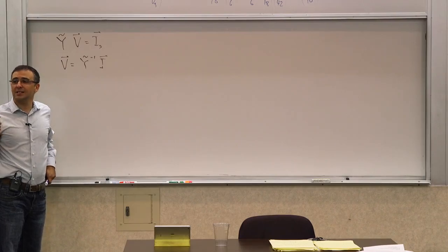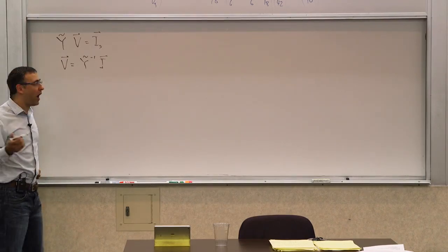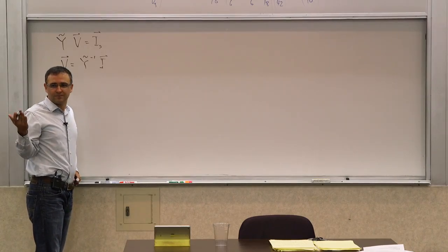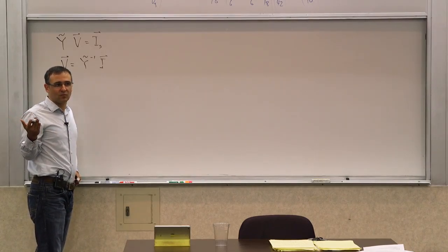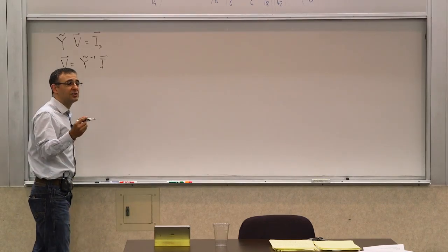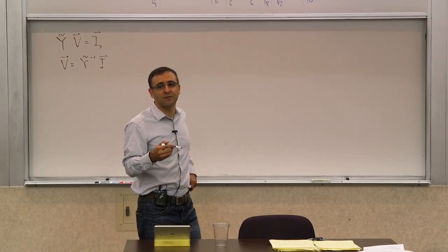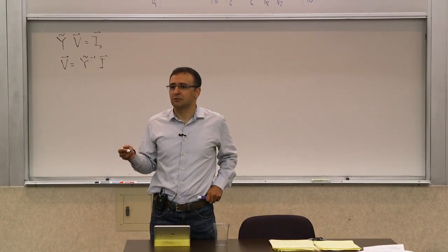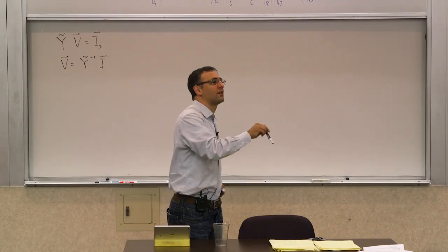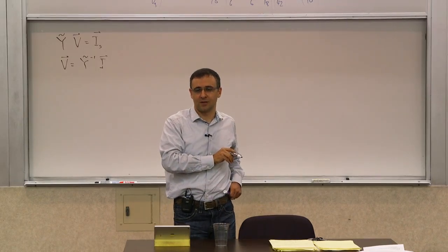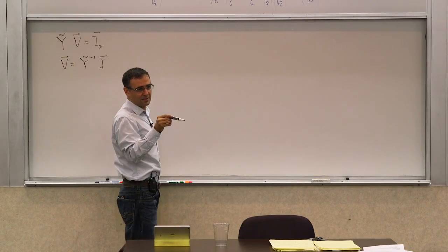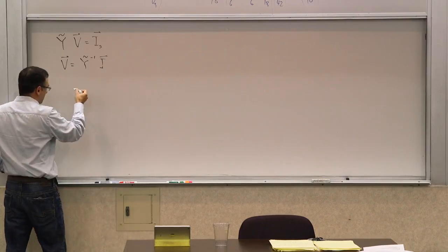So we know when a solution exists and what it means in the circuit domain. Obviously, from a mathematical standpoint, when does a solution exist? When the determinant of the Y matrix is non-zero, right? And you will see later on that the determinant of the Y matrix is important in a lot of things. For example, when you get to frequencies and natural frequencies, you will see that the natural frequencies are the roots of the determinant of the Y matrix in a circuit. So the determinant of the Y matrix plays an important role in things. But we are not there yet.